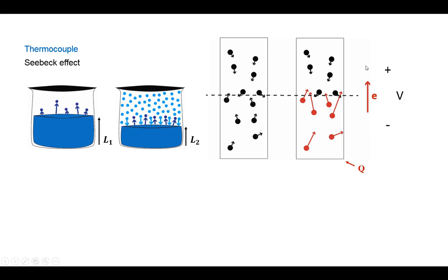and when there is a net migration of the electrons, it creates a current, and when there is a current across the resistance, it produces a voltage. So the voltage produced here depends on the type of metal we are using. As an example, copper produces a stronger voltage than iron or nickel. So they have taken advantage of this phenomenon and made a thermocouple.